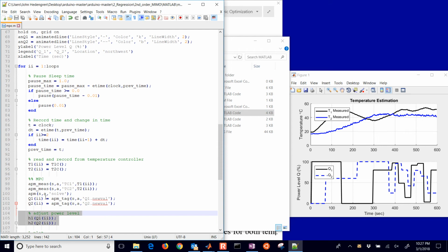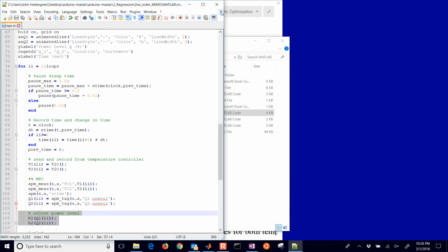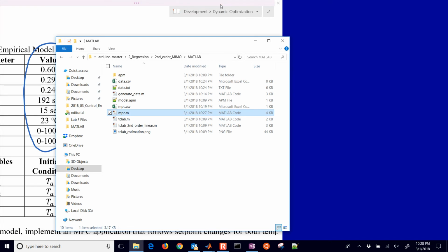Okay, I think I'm about ready. Now what I need to do is just get my new updated parameters from my estimation over here on the right. So there you can see the two trends there. There were some step tests that I gave, with these heater values, and then some random, very frequent updates. I'm going to close this. I think my MPC is about done.